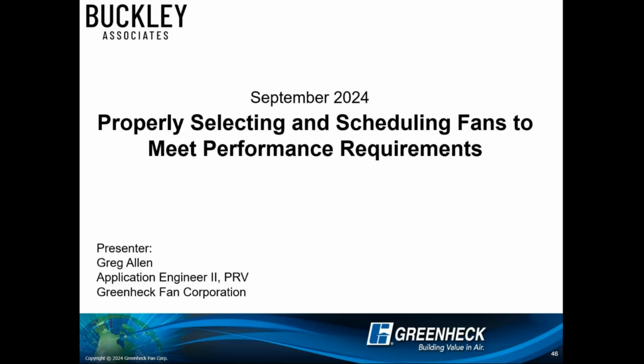So when I'm doing all that testing up front on a fan, I look at all those different points of operation and I understand what RPM I need to hit to have all those intersect, right? So I just know a final RPM. I know I need this fan at 1,000 RPM, and that's really what our selection software is doing. It's backward engineering what you're asking for. You're giving me the final output, and I'm calculating the input. So, you want this fan to move 1,200 CFM at 2 inches?